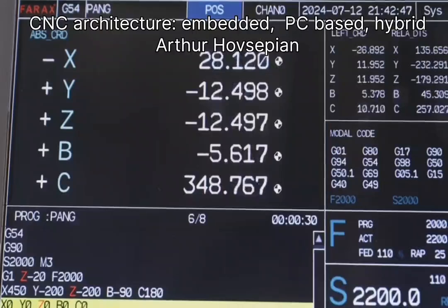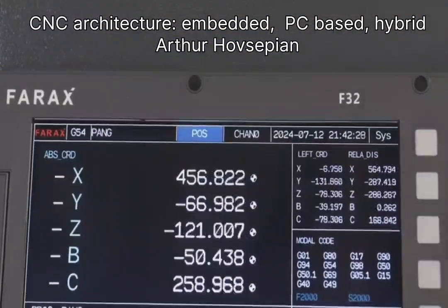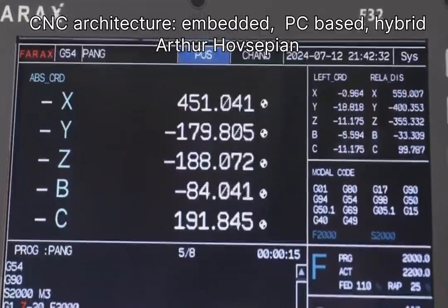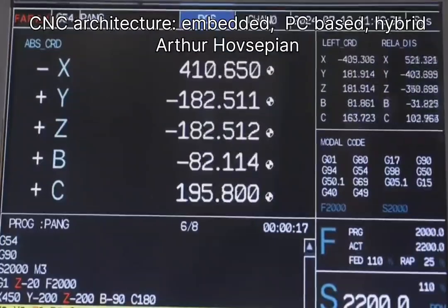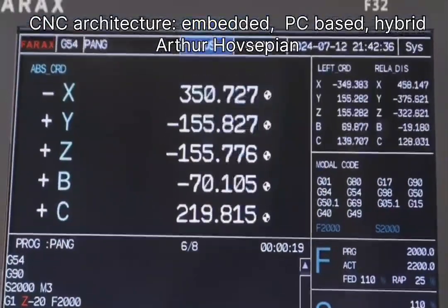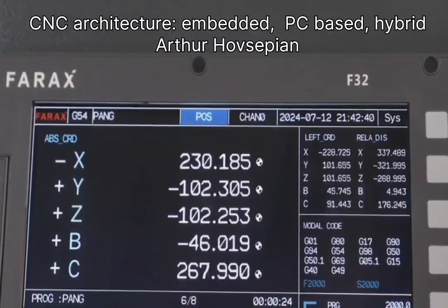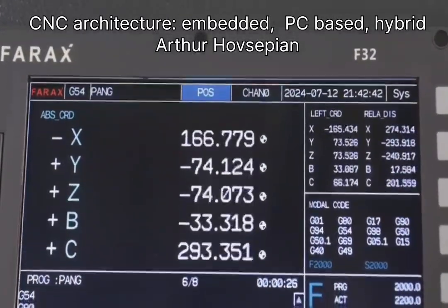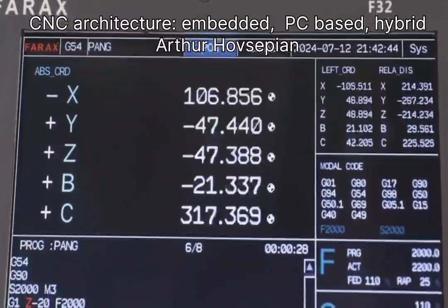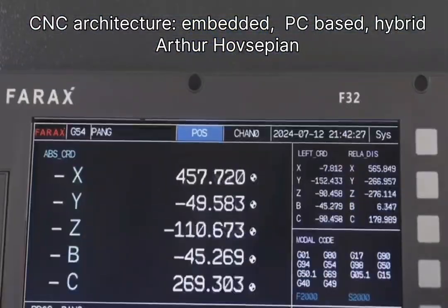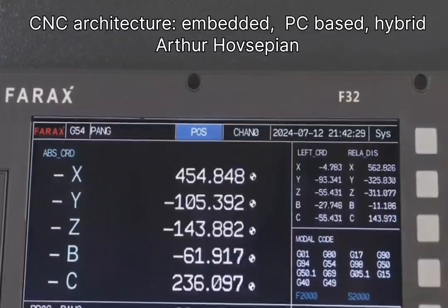But that reliance on a standard OS, we've all had Windows crash, right? How does that translate to a factory floor? That's the Achilles heel, really, because it's not a real-time system and it doesn't have those layers of industrial protection. It's much more vulnerable. Vulnerable to what, specifically? Electrical noise, delays in response time. Performance can be unstable. Things that might be annoying on your desktop can be disastrous in high-precision manufacturing.